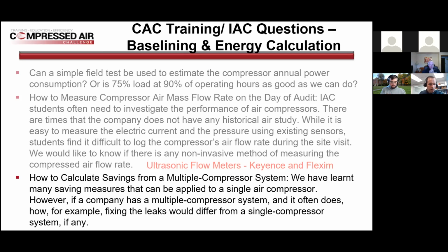One of the specific questions here is on fixing leaks and how would that differ from a single compressor system. For fixing leaks, I don't think that actually would matter, because again, we're talking demand side. You do want to eliminate all those leaks that you possibly can. I think the only time you ever get into real concern, or if you will, trouble when you're fixing leaks, is if you got it low enough where you have a base load centrifugal that was always blowing off because you got into too low of a condition.